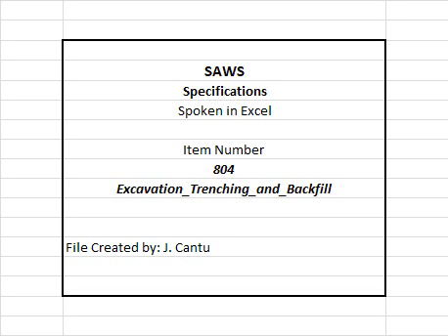Q. Whenever such maximum allowable width of trench is exceeded, except as provided for in the contract documents, or by written approval of the engineer, the contractor, at his sole expense, shall encase the pipe in concrete from trench wall to trench wall. Any additional trench restoration required as a result of an excavation wider than this maximum width or subsequent surface or paving work will be done at the contractor's sole expense.